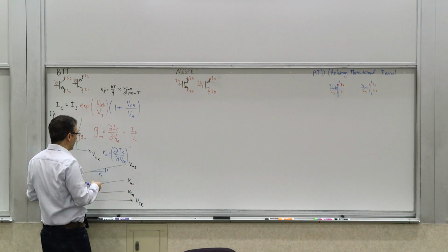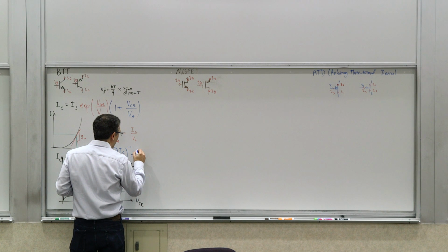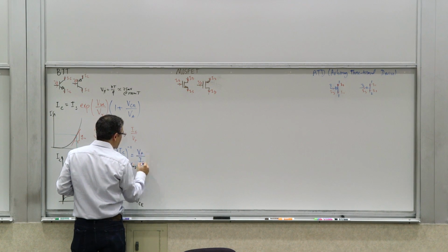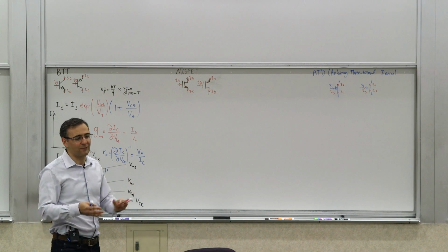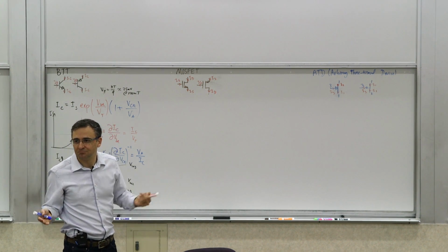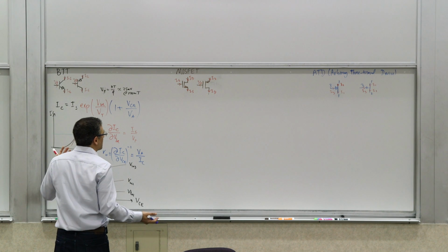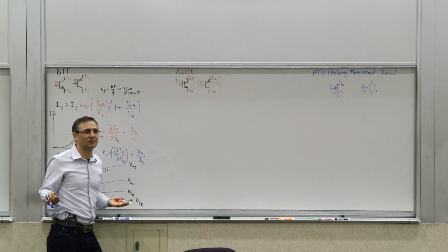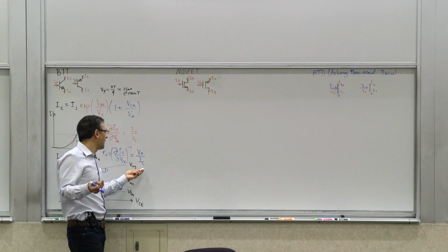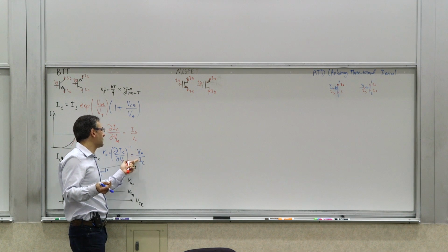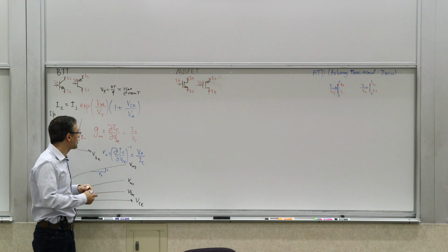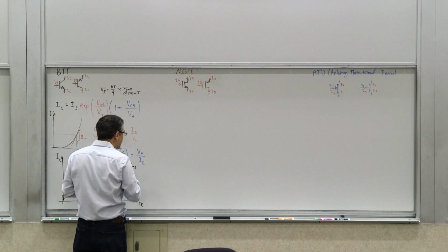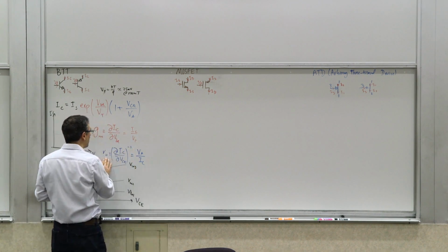And RO is also a function of VA, the early voltage, and IC. If you have a VA of 50 or 100 or something like that, it can be anywhere between a few tens to 100 for a typical bipolar transistor. At 1 milliamp, if this were 100, you will get 100 kilo ohms. So just to get a sense, remember, this is on the order of 100 kilo ohms.